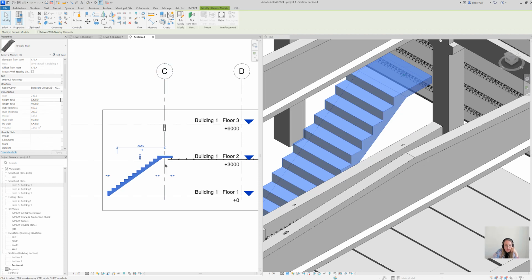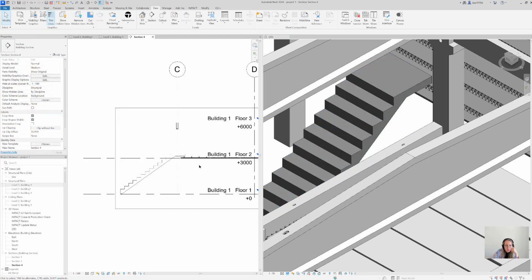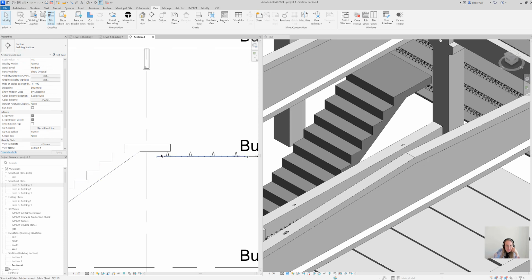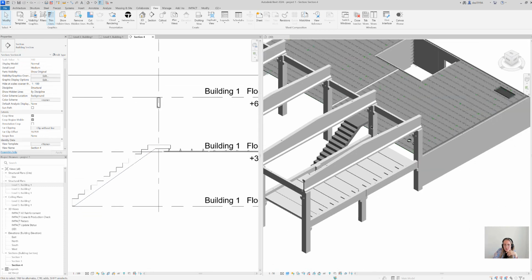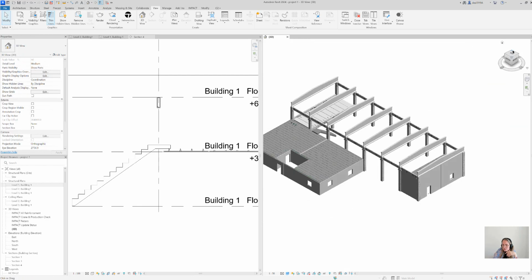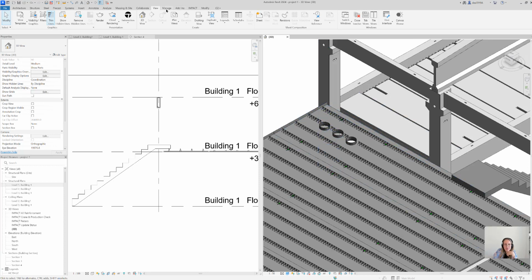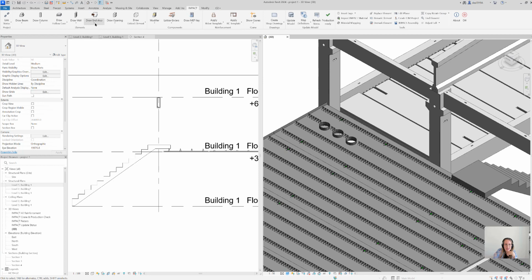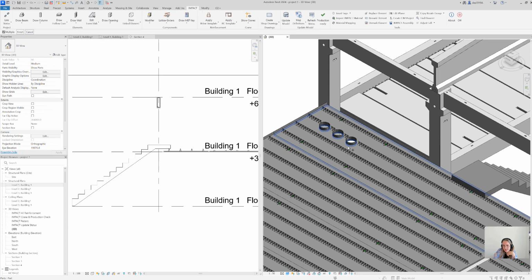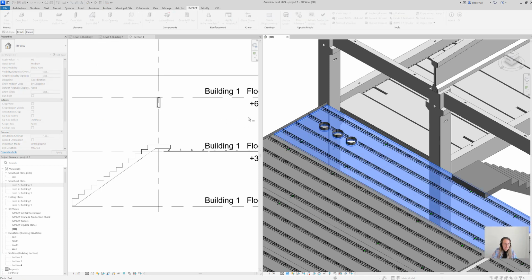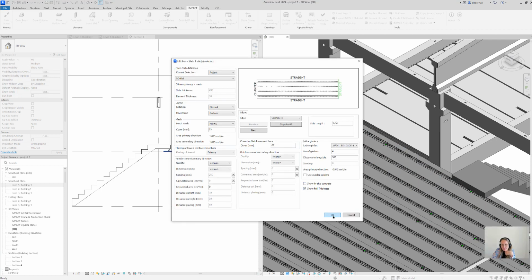3,200. And why do I change it to that? It's actually a pretty smart functionality for slabs. If I go into 3D like here, I can demonstrate it. If you select a form slab, go to Impact and say edit form slab, select this one, press finish, you can actually say show full thickness of the form slab.